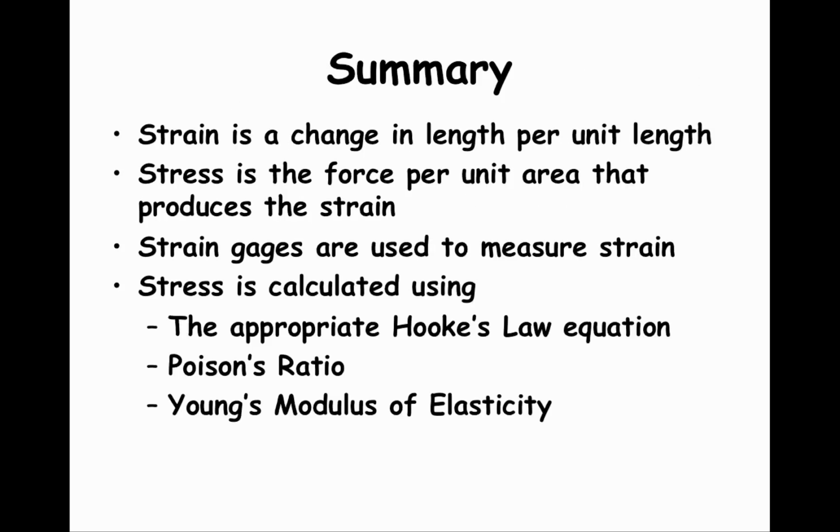Strain is a change in length per unit length. Strain gauges are used to measure the change in length per unit initial length. After we measure the strain, we calculate the stress using the appropriate Hooke's law equation, Young's modulus of elasticity, and Poisson's ratio.